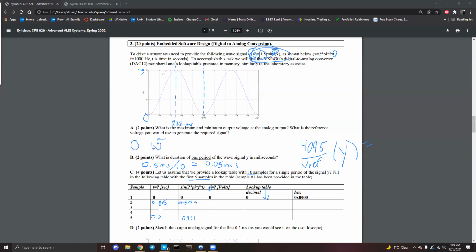Right, because that's the peak. We don't need any more voltage reference to generate 1.5 because we're not going any higher than it. So we need the minimum and the peak, but the minimum is implicit at 0. That's just how it is. So in reality, this formula looks a little different, where it'd actually be Vref plus minus Vref minus, which is 1.5 minus 0, so who cares? And then just say Vref instead.